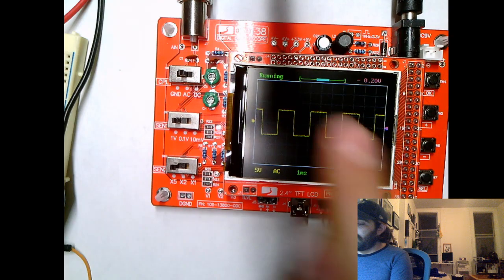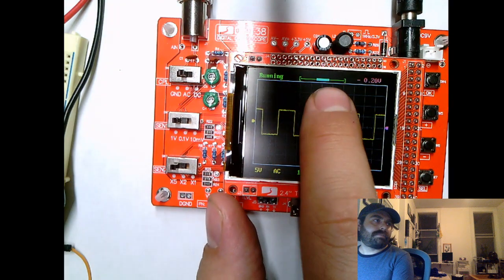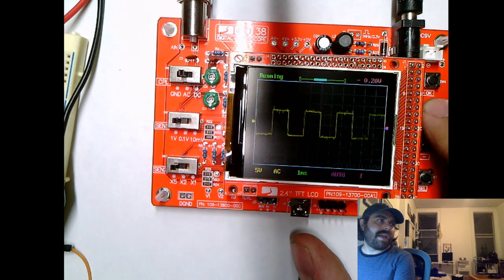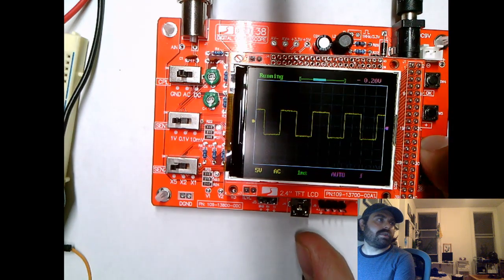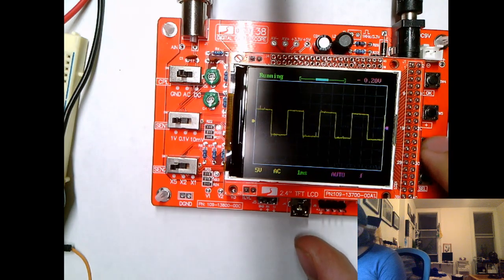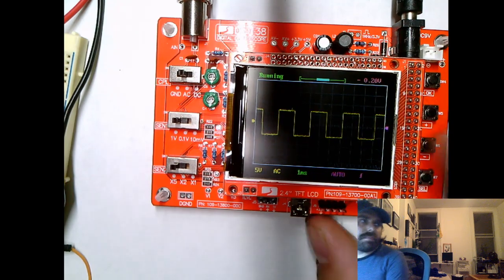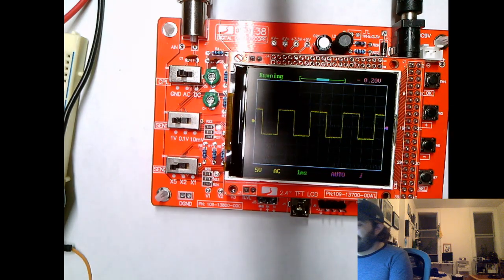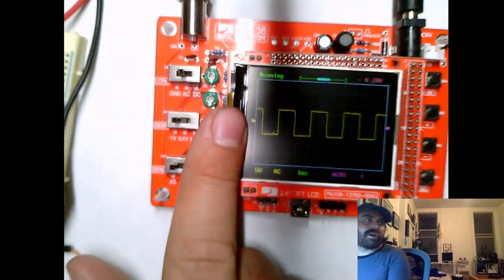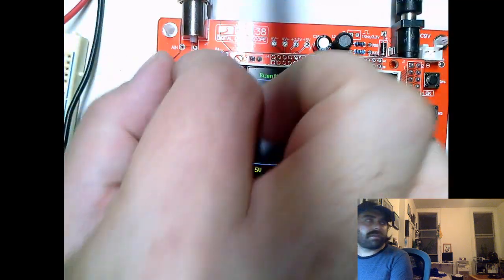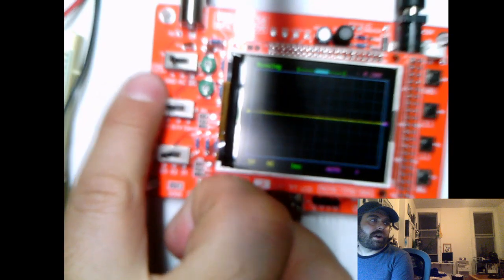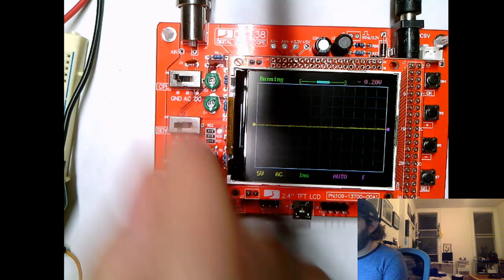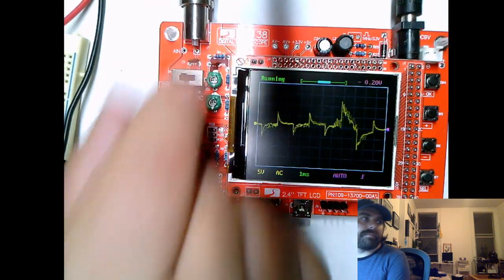The last thing I'm going to show you, I'm now selected up here, this little bar. This is my horizontal position. So I can shift my wave left and right if I want to. As far as horizontal and vertical position, you probably want everything to be at 0 so you can measure things. You might have to move your vertical position if you're not at 0 when you're grounded. So remember, ground first, check your line, and then adjust as necessary, and then flip this back to AC.